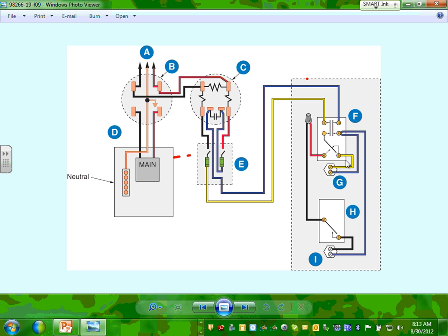The electrical load of the water heater here, guys, is a big electrical load. What the utility wants you to do, if they can coordinate the consumption of the bigger loads, they don't care about your lights. They care about the water heater, because the 5 kW load is a big chunk of the load. On average, your house cannot consume more than 10 kW. The water heater can be half of that.